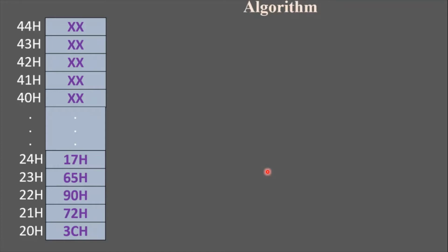Now, one thing I would like to tell you is that these all are internal RAM locations, and RAM memory is also called a data memory. What is the speciality of these locations? These 5 locations are continuous in nature. Similarly, these 5 destination addresses are also continuous in nature. You cannot transfer all 5 numbers from source to destination. You have to do it one by one.